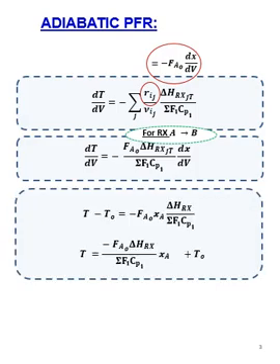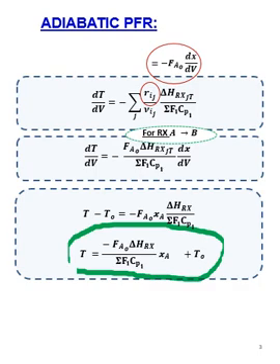For a reactor where X is equal to 0 at the inlet, if I integrate from T0 to the temperature at any point in the reactor, and X goes from 0 to X at any point in the reactor, I can prove that I once again get a linear expression for temperature as a function of X. That is of course provided that delta Cp of the reaction was pretty much equal to 0, and that delta H of the reaction, as I integrate, is not a function of temperature.